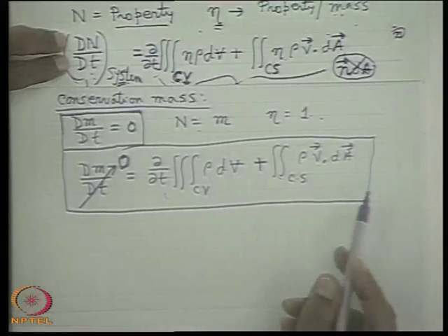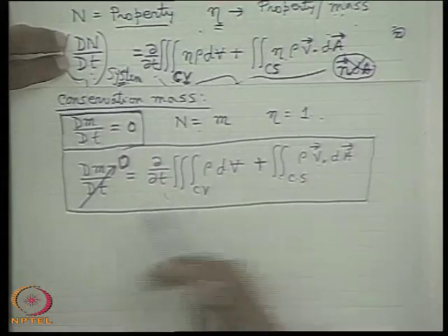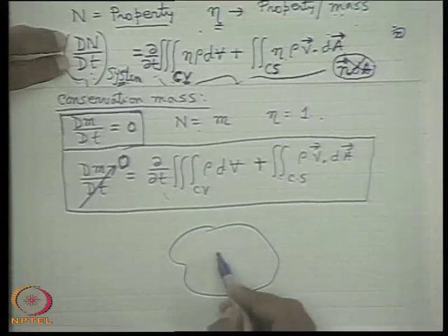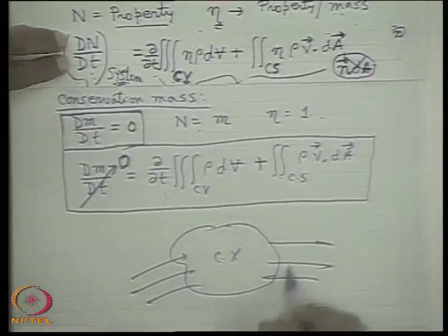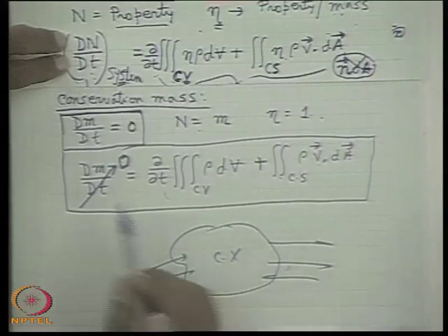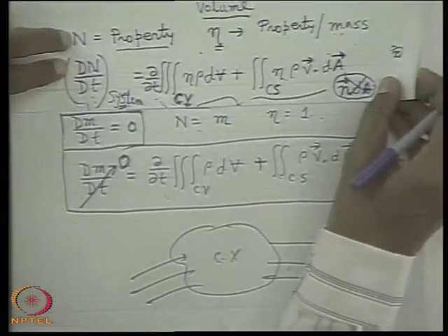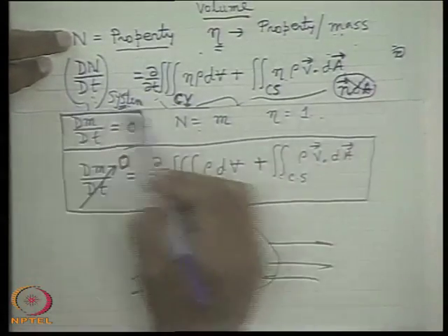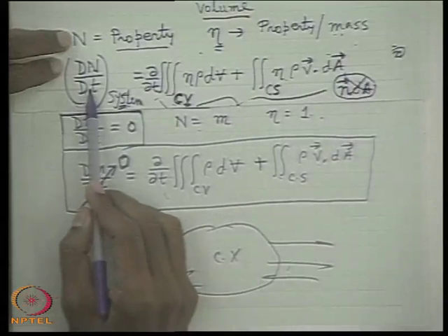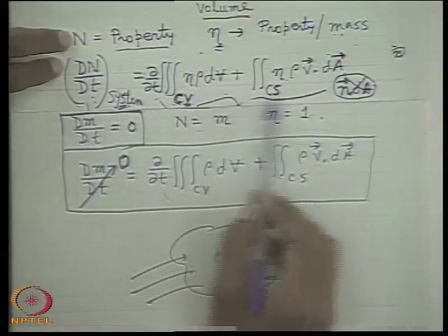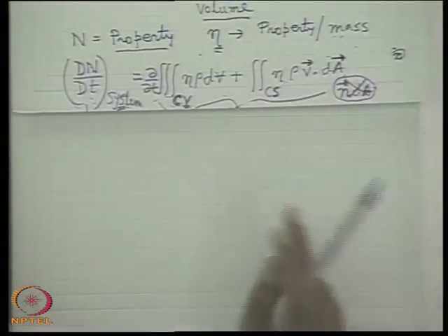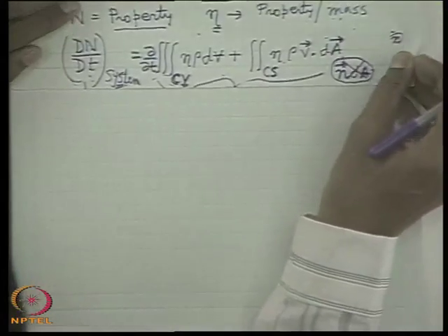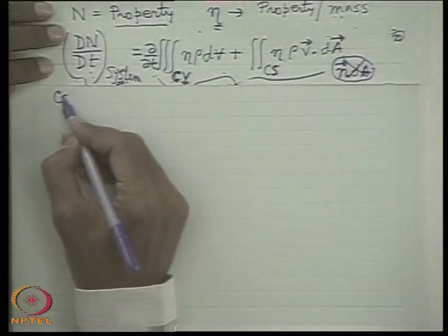A boy at school level can tell what is the use of all this theorem. It comes from common sense, that if there is a control volume, a fixed region in space, where mass is coming in and going out, the balance must be accommodated by the control volume. But this may not be so from simple intuition for other laws, so we have to recall the Reynolds transport theorem, which relates the change in property of a system to that for a control volume. Now let us see what happens for the conservation of momentum, which is not so simple. Let us write the conservation of momentum.